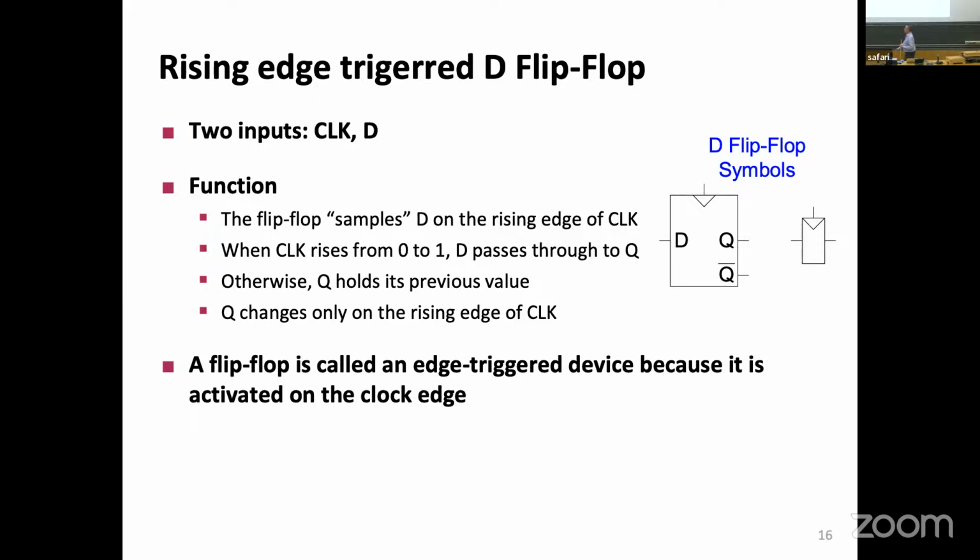Whenever there is a change in the clock signal, so if my clock goes like this, 0, 0, 0, and then it rises, in a latch, you could say that during this time, the input will be connected to the output, and here I will keep the data stored. What if I could just memorize at this instant, this very short time?